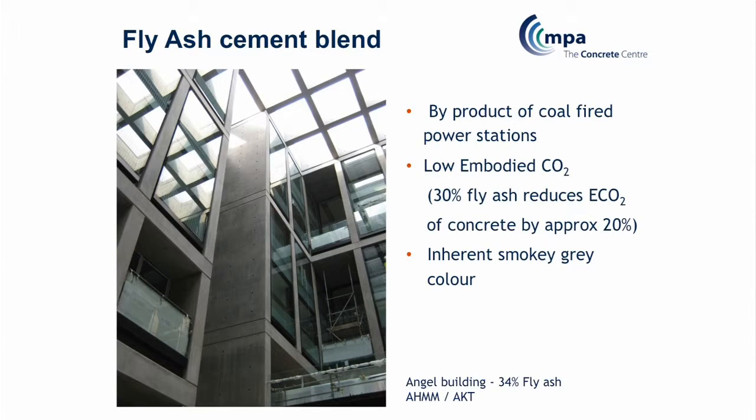The other very commonly used cementitious addition as part of the cement blend is fly ash, and that's a byproduct of the coal-fired power stations. Again, low embodied CO2. A great example of this is the Angel building, which used a 34% mix, and that's a great building to go and have a look at for visual concrete too. So a key consideration when you are thinking about specifying concrete is to consider using cementitious blends.